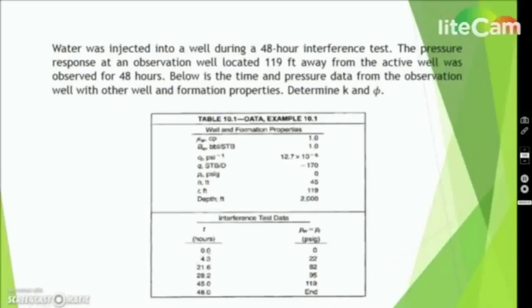The data for times and wellbore pressure are already given here. For the first data, time is equal to 0 and wellbore pressure is equal to 0. Since we are going to plot a log versus log graph, we can ignore this data. And at the last data of wellbore pressure, it is stated as N. We cannot plot it, so we just ignore this data. Then from these 6 points of data, we only take 4 data to be plotted.